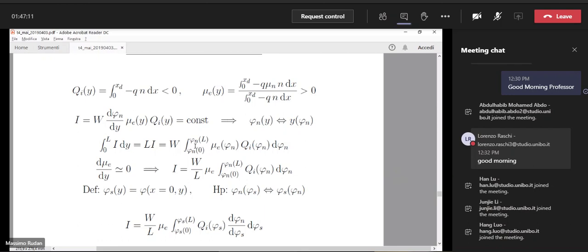And then you remember, we analyzed this in the MOS structure, the field in the insulator is proportional to the field at the surface of the semiconductor, okay? And the proportionality factor is the ratio of the permittivity of the insulator and the permittivity of the semiconductor, okay? So the question is this: is the vertical component of the field inside the insulator the same at each position of the channel, or does it change when we move from one position to the channel to another?